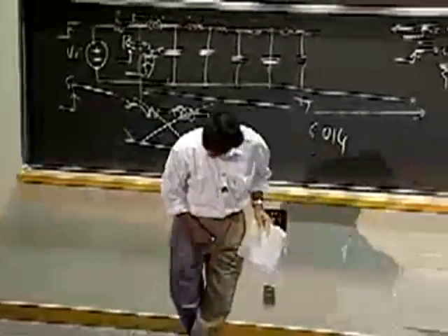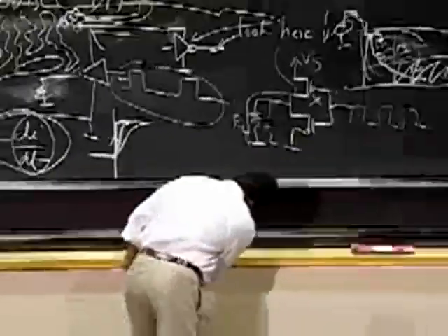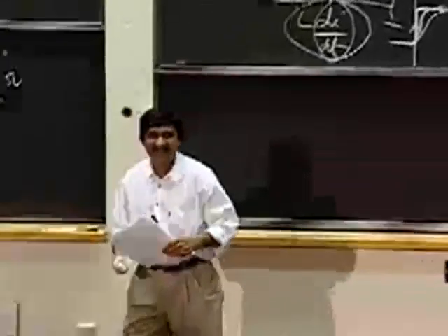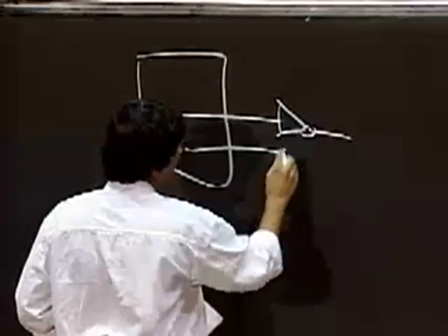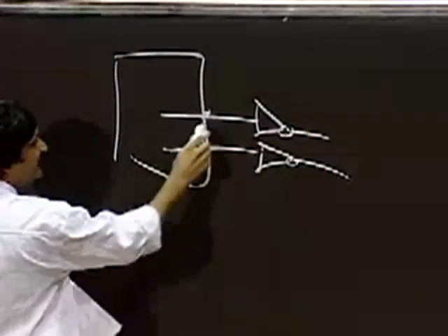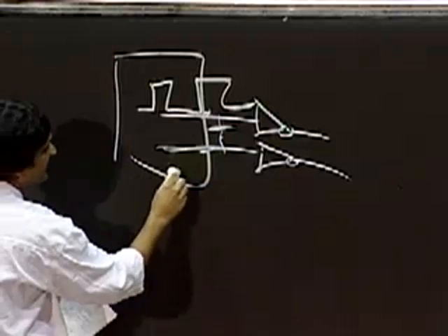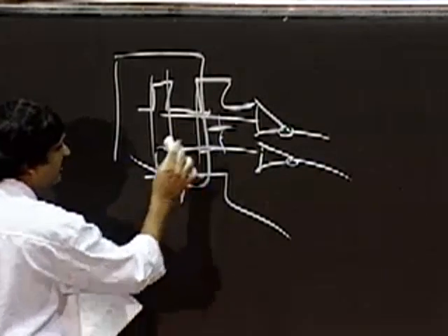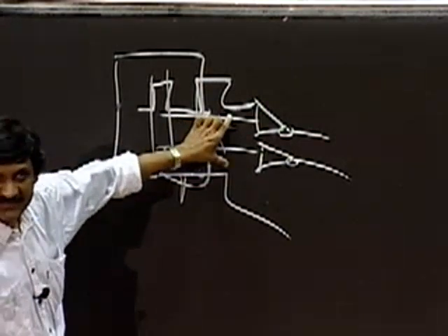If you remember the demo from the lecture about a month and a half ago on capacitors, I talked about a chip with 2 pins, and there was capacitive coupling between the pins. Because of this, if this waveform is switching, then because of this coupling, if this is the signal here, you will end up getting spikes on this pin because of the signaling of the other pin. And that's good old capacitive coupling.